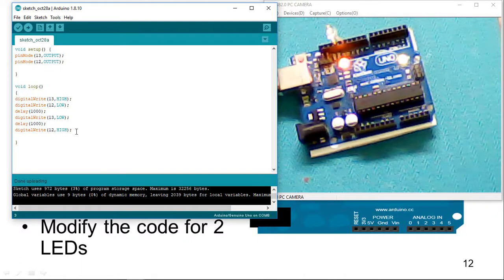What's happening here is I write high here, then it repeats and it becomes low, and it stays low for a second, it stays low for the next second, then it becomes high and low again. So it stays high for a tiny fraction of a second, which means the second usual suspect, the sequence. I put my line after the delay, it should be before the delay.